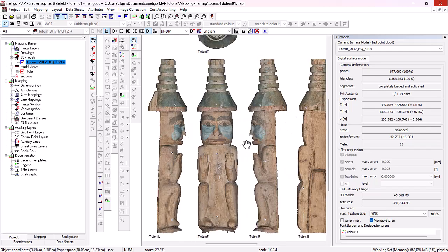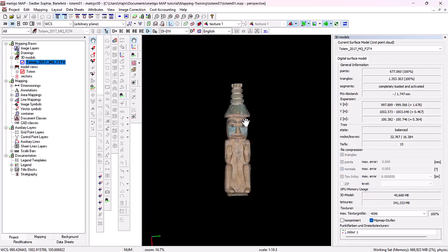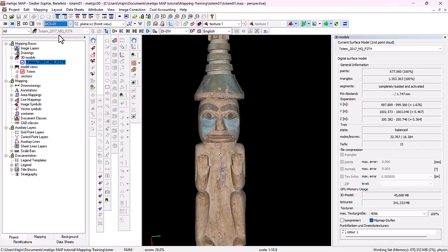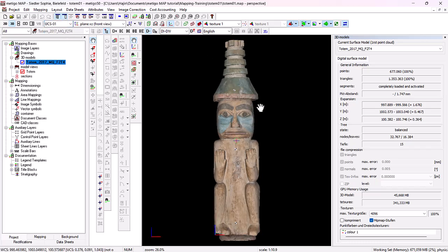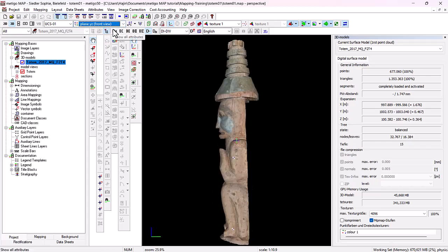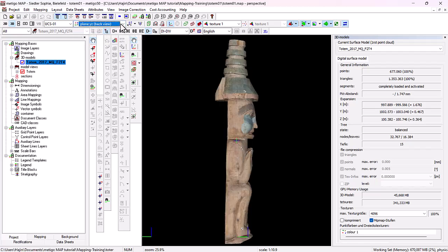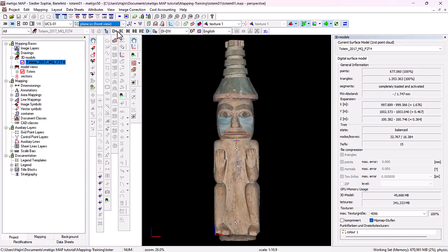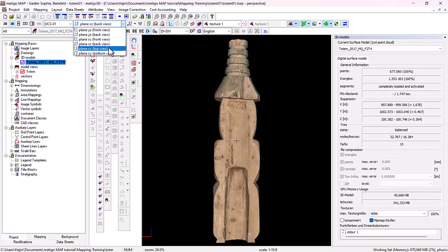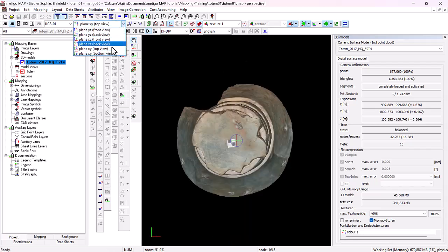As you can see here, you now have a vertical display defined in the coordinate system to create an unwrapping of the totem. So when I've selected my user coordinate system, I can then use the second pull-down menu to select the different 6 views. That is, I have the front view, YZ, the rear view of it. Then I have the front view of XZ and the rear view of it as well. And then the top view and bottom view.